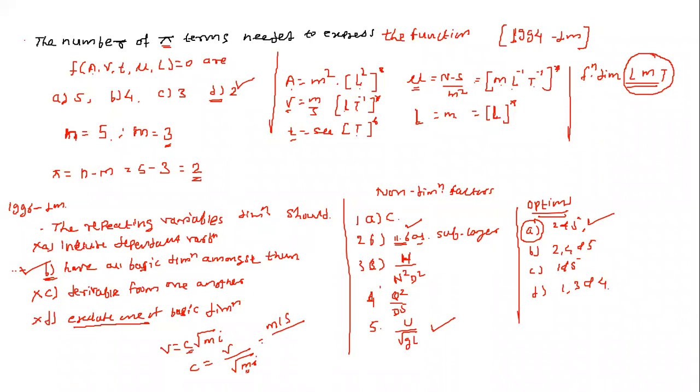Okay, r is equal to a by p, area by perimeter. Area will have the unit of meter square and perimeter will have the unit of meter, so meter square by meter will have the unit of meter. And i, that is the slope, will not have any unit, meaning meter per second by root m will be there. This is not a non-dimensional parameter. There will be some unit. So the first one, Chezy's constant, is not a non-dimensional parameter.